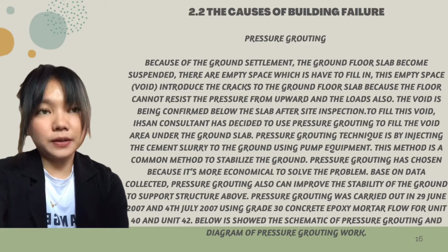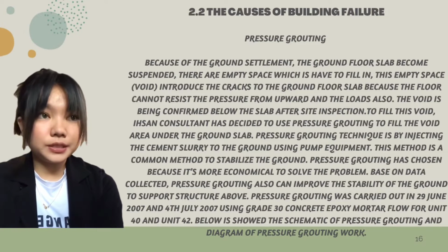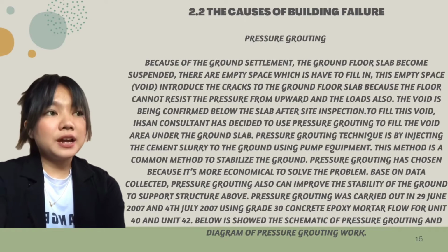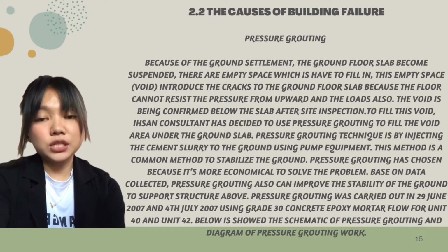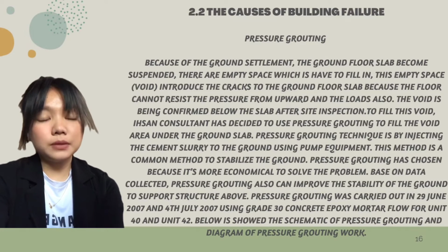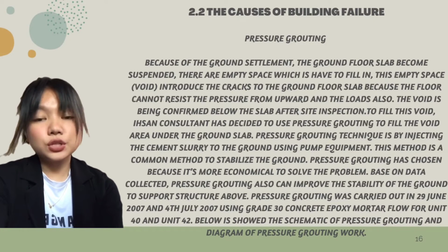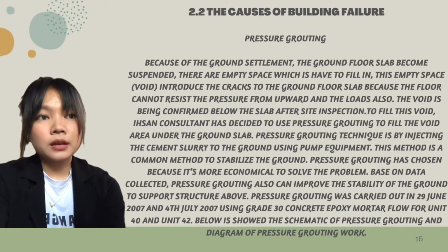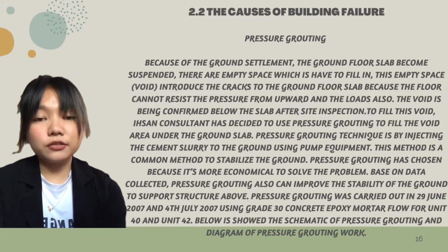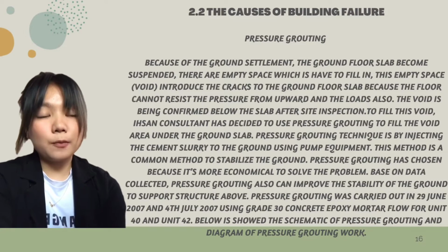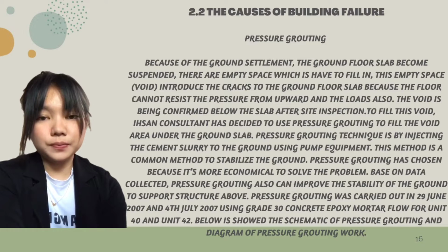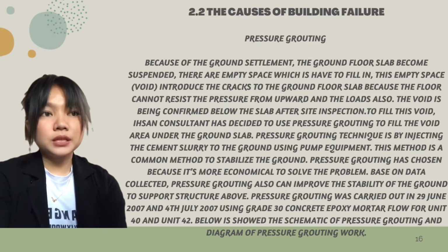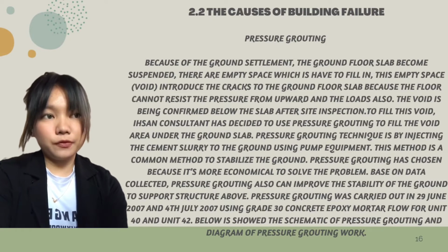Pressure grouting. Because of the ground settlement, the ground floor slab becomes suspended. There are empty spaces which have to be filled in. These empty space voids introduce cracks to the ground floor slab because the floor cannot resist the pressure from upwards and the loads also. The void is confirmed below the slab after site inspections.